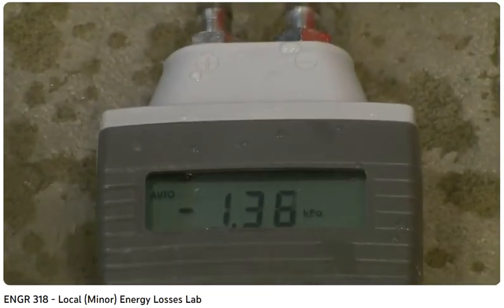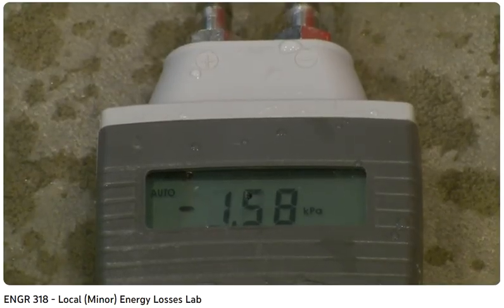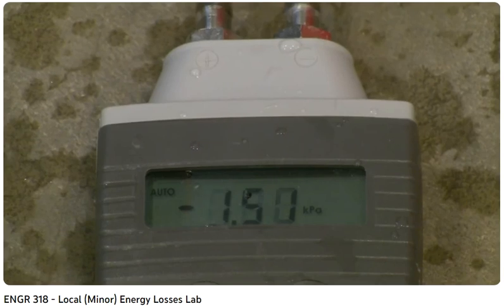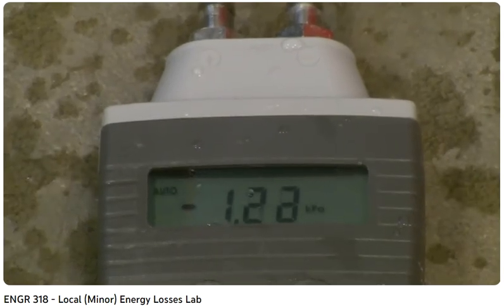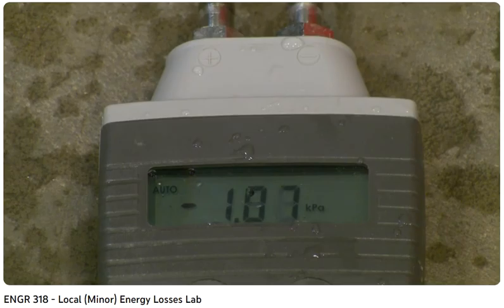And so what you need to do is take some pressure measurements there. It's jumping around a bit, and the way that we handle that and overcome it is with a temporal average. So you'll see several different values. Enter 5 or 6 or 10 of them into your calculator, and then take the average of all of them. I'll do the same. I'll write down some values on my page, and later on I'll take an average so that I know the average drop in pressure through this fitting.